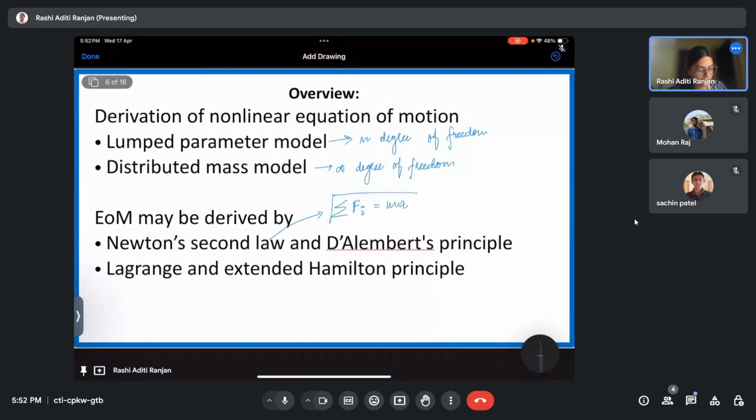This is Newton's law. Everyone knows it. It's a very simple law, and we learn it in the very initial days. Right. Now, when I talk about D'Alembert's principle, it is nothing but an extension of Newton's law, because here we take a static equivalent of my dynamic system. Simple: I'll just take my ma to the left hand side and write it equal to 0.